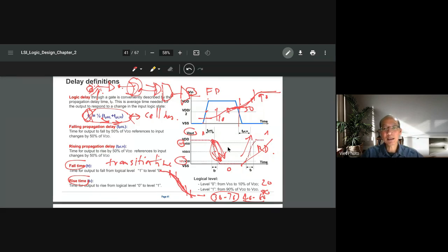Because of that, there will be some problem with the circuit. Let's say the clock. The clock is not one cell; it will be multiple cells, and if they behave like this and like that, it messes up the clock tree. So one of the requirements for the clock cell is to have balanced rising time and falling time.